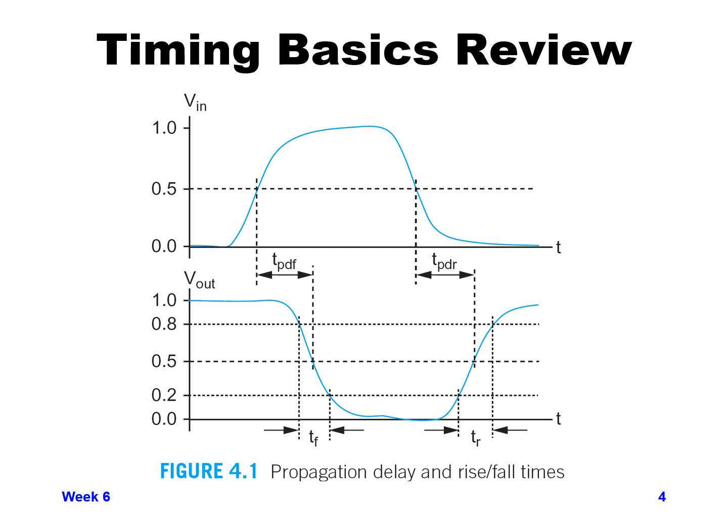to 50% output rising, and the rise time will be as the output is rising, once it hits its 20% point, and we start measuring. Once we get to the 80% point, we stop, and that is the rise time, or also the rising slope. So just keep that in mind as we go to the following foils.